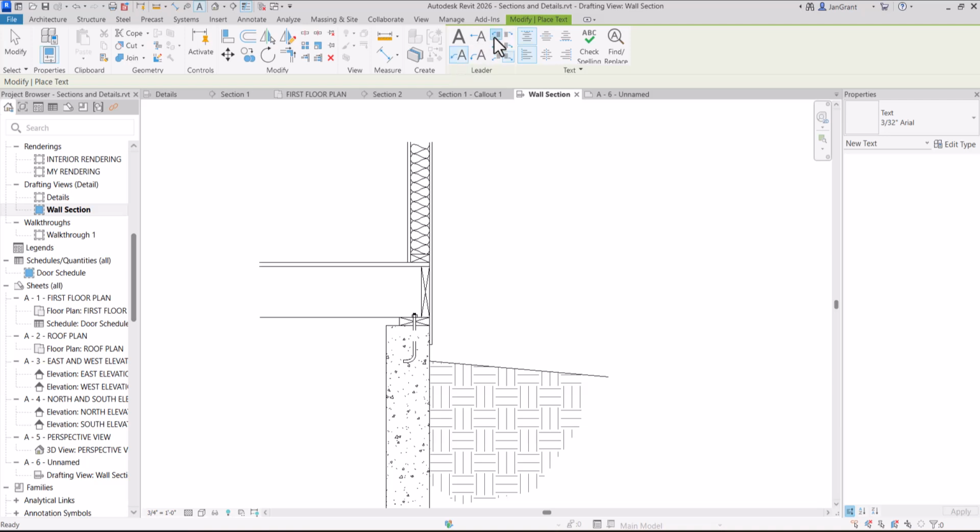And then we want the top leader at top left, right? And when you just move your pointer around, it'll say at the bottom left corner or on your pointer, specify leader points. So we'll just add one note for you to work with, and I'm just randomly going to pick the wood, the sill, mud sill.